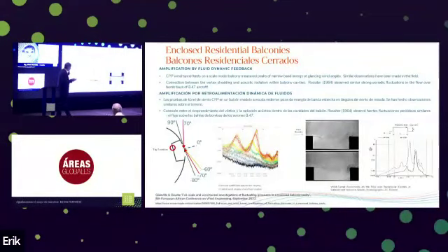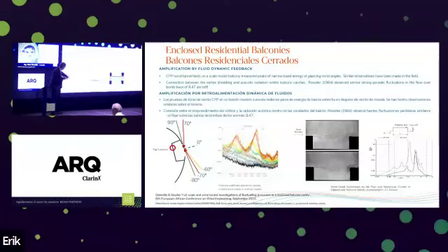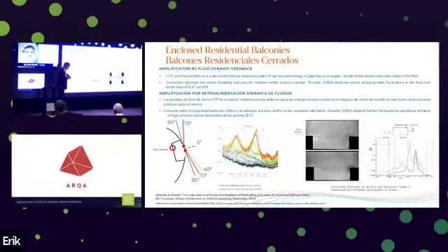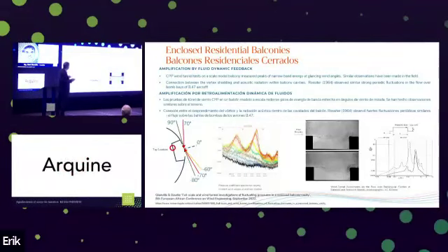One of the studies we investigated in a wind tunnel model is a recessed balcony, measuring wind pressures inside the balcony walls. It's an enclosed cavity, and the pressures are found to have this narrowband response. There's a connection between the vortex shedding and acoustic radiation within the balcony cavities occurring at the opening for glancing wind directions. And this has been found in other fields previously.